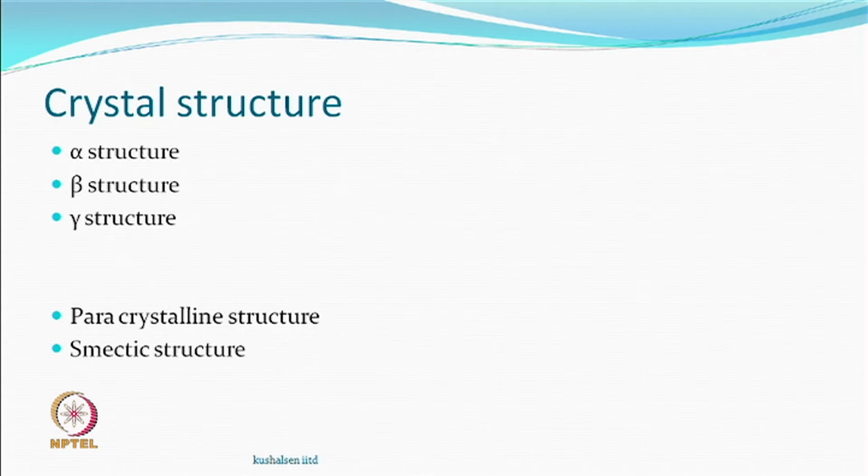And polypropylene, which we said is also a good material for texturizing, can actually have alpha, beta, gamma type of crystal structures. Some materials like acrylic do not really show very highly defined crystals, without flaw, without any defect, and therefore, in general, their crystalline structures are somewhere in between, not amorphous and not fully crystalline, but what we call a paracrystalline structure.